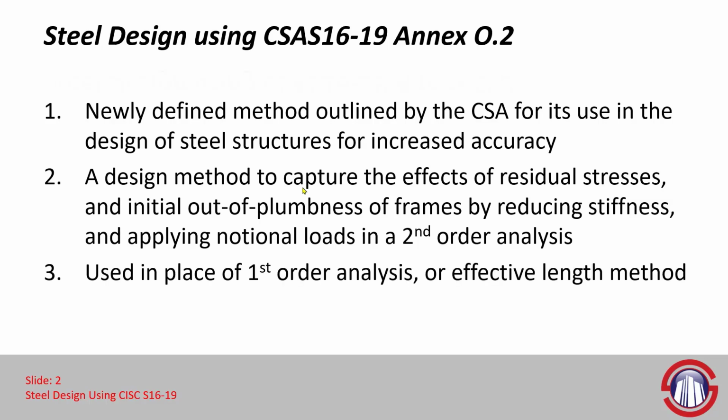And this approach is used instead of a first order analysis or an effective length method. And one of the advantages of this is that it relegates the task associated with residual stresses and effective length factors to the finite element solver. So it reduces the amount of work that's required by you to assign effective length factors and whatnot to your model.